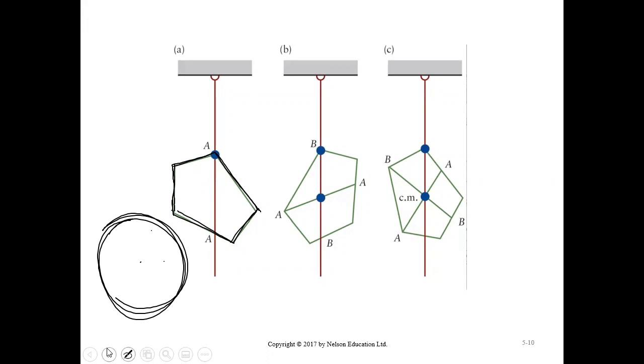This is the method for finding the center of mass experimentally. What we do, we take a point in the periphery and tie a string to that and hang it. So the string will hang vertically, right? So you extend this vertical line, take a pen and draw this extension, and I'm going to call it AA. So let's say I draw it in black. I draw a line on the object by hanging it at the point A and extending that vertical line, you got this black line.